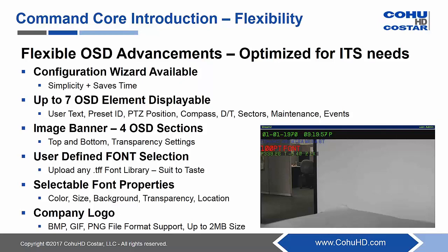So we've built in a number of things to allow the user to be able to do that with the Rise product, replacing some older technology. As well, the OSD has a configuration wizard available just to simplify the configuration of all the OSD displays. We offer up to 7 OSD elements. An element is a separate OSD function such as user text or a preset ID, the position the camera's looking at, a compass direction. You could add the date time. You can have the sector title giving an indication of the view that the camera's looking at.